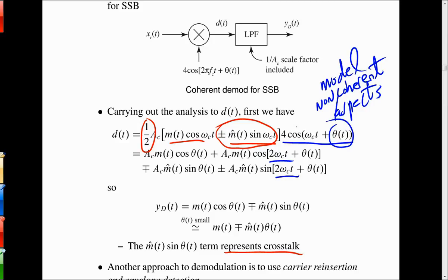So you get used to that idea in this class now. We know how the frequency domain works, and as long as those double frequency terms can be separated from the baseband terms, which they can be if the omega c is high enough, and then 2 omega c is even higher, we just assume we have a low-pass filter that can do that separating.